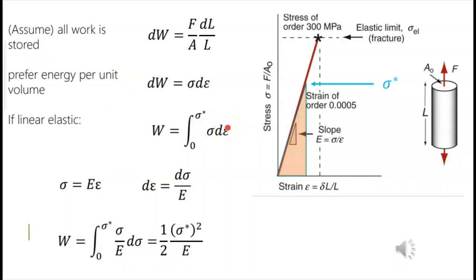Now, when we have a look at the modulus of elasticity, it has this formula. Sometimes this formula is written as elastic modulus is stress over strain, where stress has a unit of megapascal and strain has no units. So the unit for the elastic modulus is going to be the same as stress, megapascal, sometimes gigapascal, but mostly gigapascal.